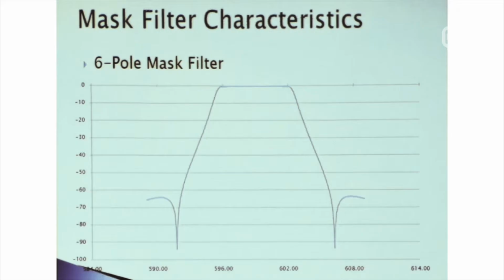So what that says is that we can expect to find each of the 50 kilohertz samples at minus 57 in order to end up with 10 of them being at minus 47. And so that's why this is showing here at minus 57. So that's the signal that we're starting with coming out of the transmitter.